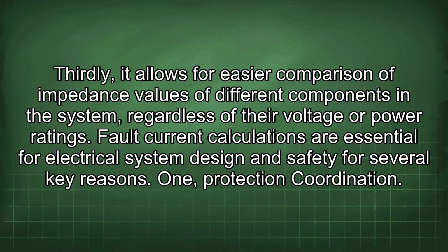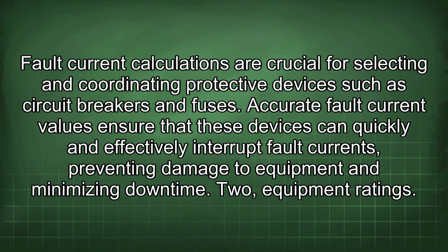Fault current calculations are essential for electrical system design and safety for several key reasons. 1. Protection coordination. Fault current calculations are crucial for selecting and coordinating protective devices such as circuit breakers and fuses. Accurate fault current values ensure that these devices can quickly and effectively interrupt fault currents, preventing damage to equipment and minimizing downtime. 2. Equipment ratings.